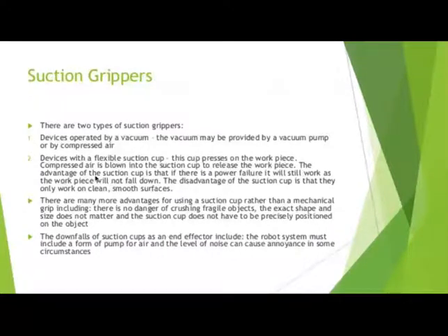The advantage of the suction cup is that if there is a power failure, it will still work, as the workpiece will not fall down. The disadvantage of the suction cup is that it only works on clean, smooth surfaces.